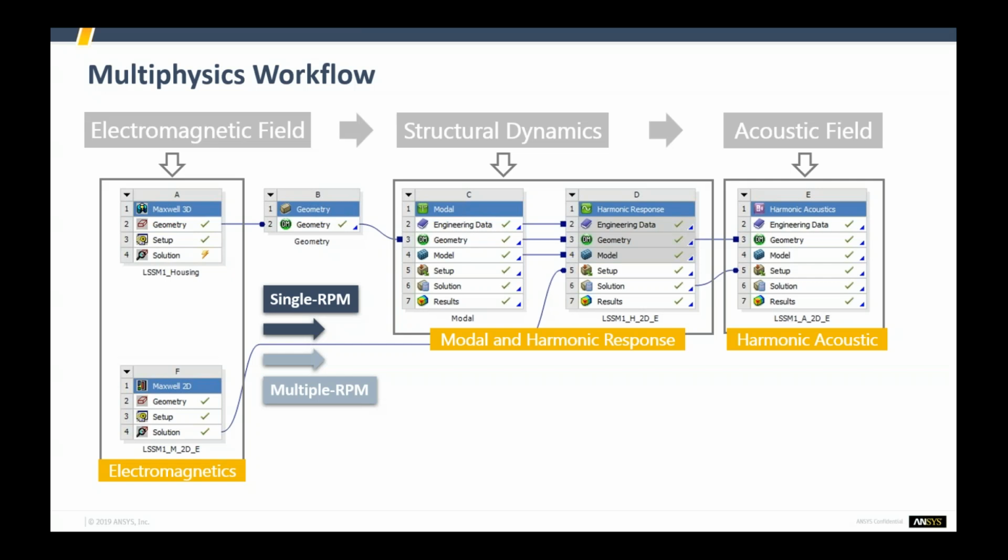If your H mean is really small but your H max is not small enough, the time step would vary based on your setup and your model. Say your H mean is 50 microseconds and your H max is 100 microseconds. Sometimes the time step would be 75 microseconds. So it would take a middle point in between the H mean and the H max. That's something you want to pay attention to.